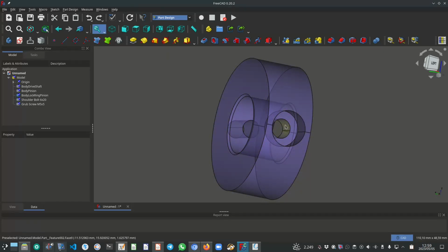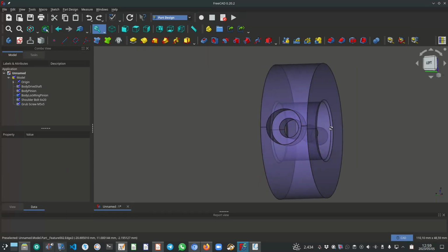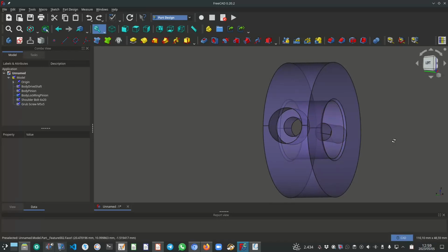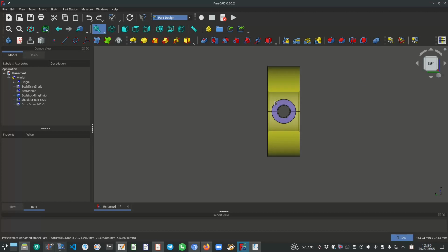Its location, its orientation, its roundness or cylindricity, all those features are very important. Since this hole is symmetric between these two faces, it is a logical decision in my mind to make the symmetry plane another datum. So we will have that cylindrical surface as one of the datums, and in this case the symmetry plane as another datum.